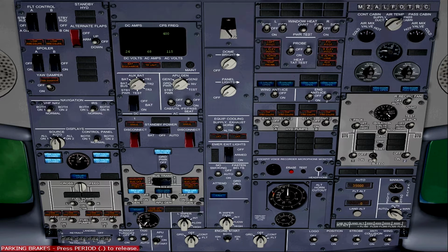It's going to do that once it reaches up to the 8. So it's climbing right now, going up to 6. It's going to keep going. So all I have to do is just wait for that. Okay, now APU gen off bus is illuminated. Click the on and on for these two outer switches around the light.